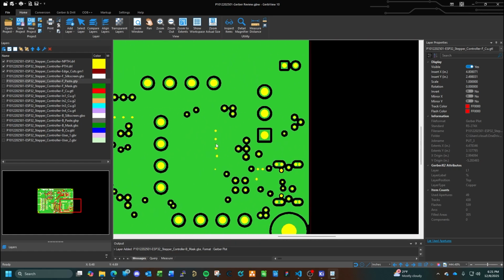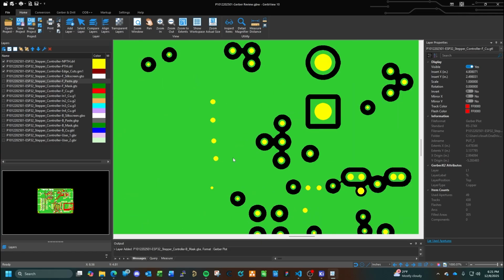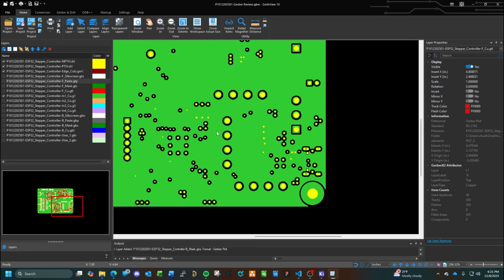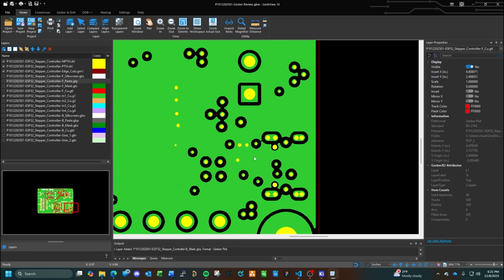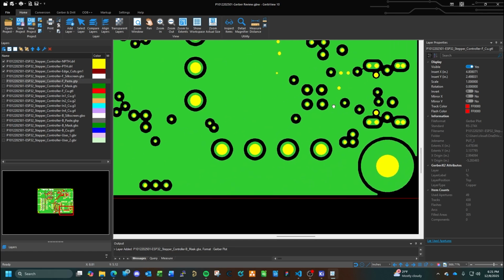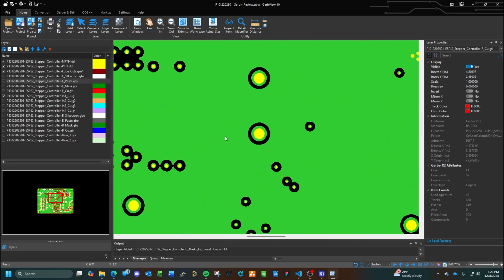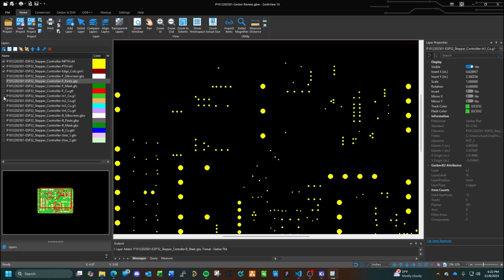But you'll see like your vias right here that are popped through that are tied straight to 3.3. So the big opening around it means it's not tied. That's basically you're punching a hole through it. Nothing's connected. But right here you see your via drill, but it's actually solid. So you got a via that ties into that. That's what you're looking at here. So you want to kind of just make sure that holes are clear, concise, punch cleanly through. So that's your 3V3 line.